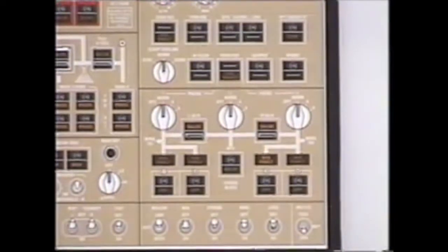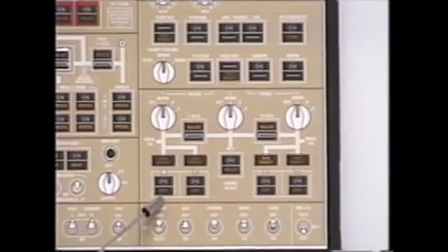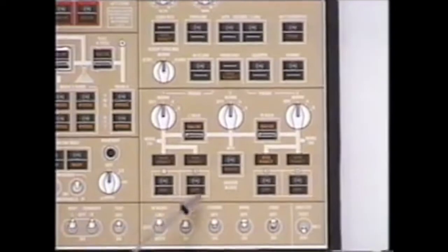As far as pneumatically driven items and where they get their air source from, on the engine prior to the bleed valve, there are 2 components on each engine that are pneumatically driven using pneumatic air from that engine. That would be the engine starter and the nacelle anti-ice.